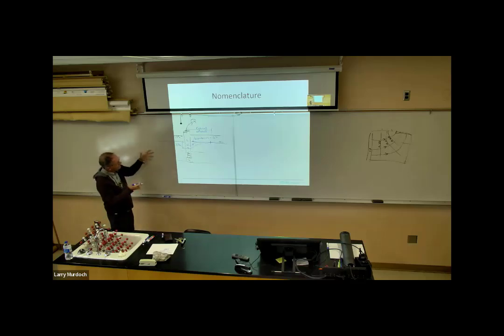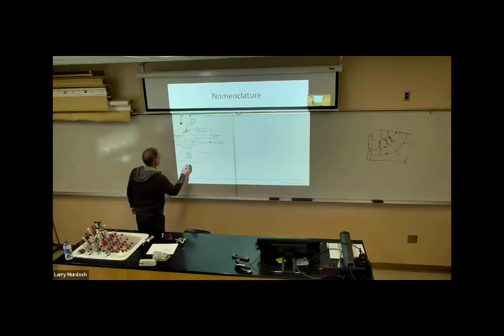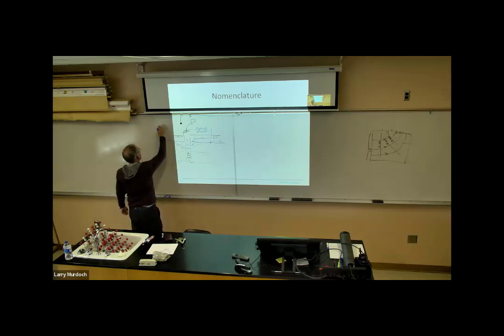And that has a cone shape. So this thing is called the cone of pressure. So that's the overall region around the well where the drawdown has occurred.